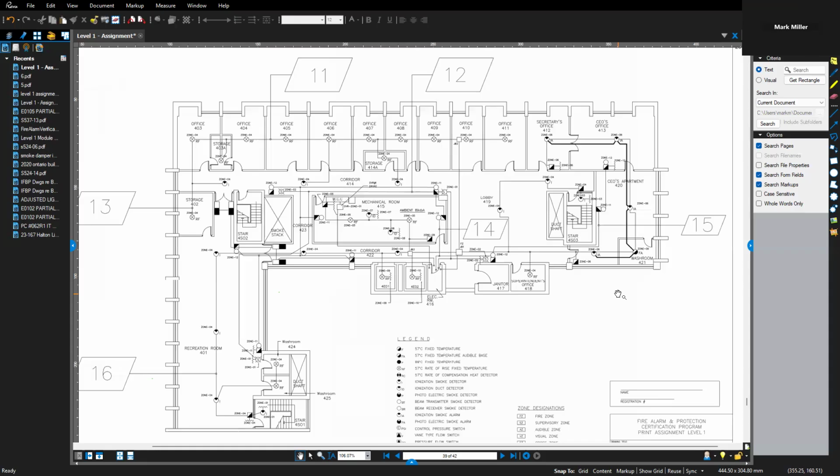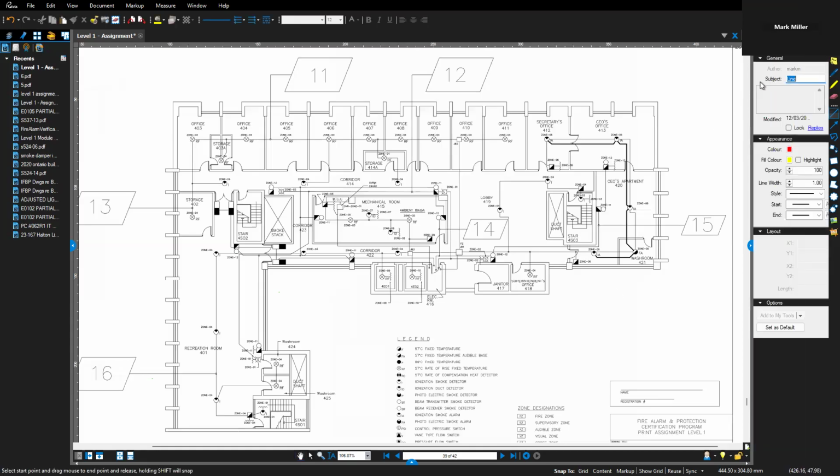One of the things that I like to do when I start any fire alarm project, right, you get handed drawings like this, you gotta start by familiarizing yourself with the building. And so one of the things I do is I draw in all the fire separations. Because I'm a creature of tradition and I've been doing it like this forever, I use pink for fire separations.